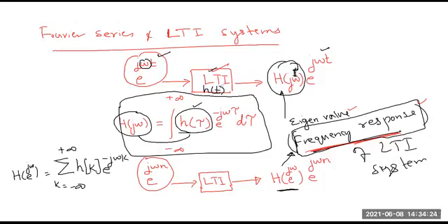But impulse response is a function of time, and frequency response is a function of omega. That is one important difference: the frequency response helps us transform a time domain property, which is the impulse response, into the frequency domain. And in order to perform this transformation, you have to make use of this integral.